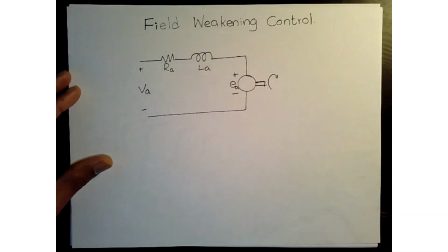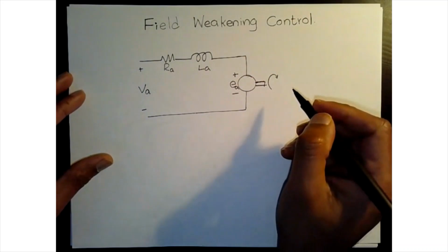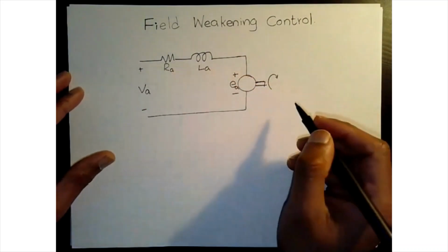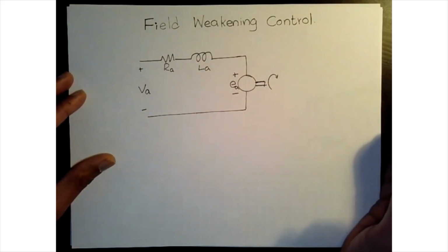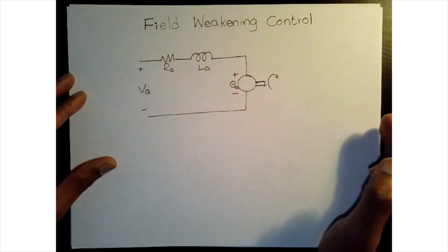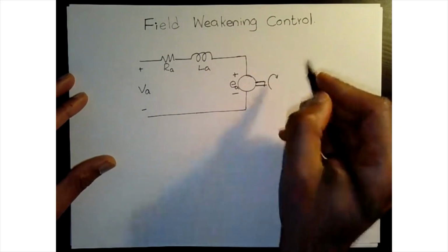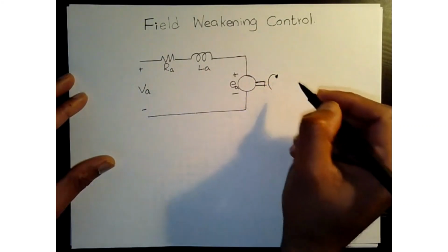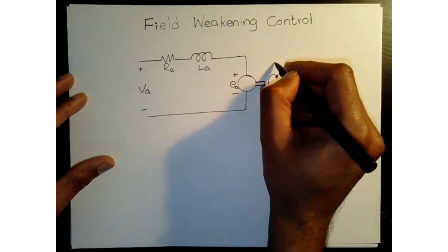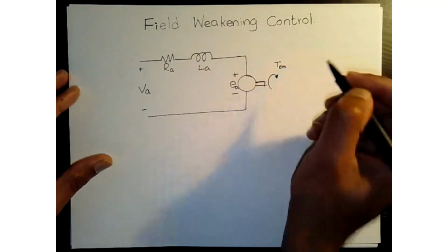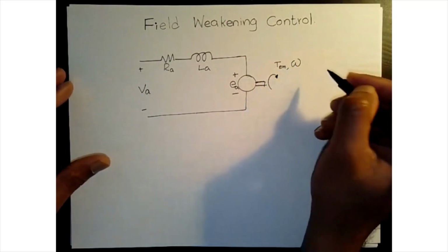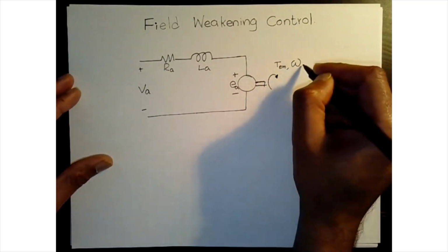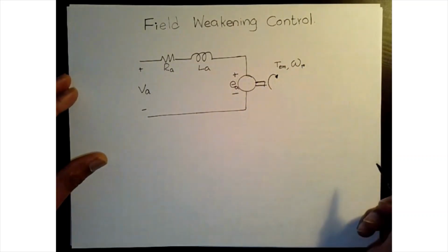Okay, yeah, so the torque constant, of course, right? Torque constant, which in terms of value is the same as KE, the back EMF constant, right? We know that under SI units, KE and KT are the same, or almost close. Not exactly the same, they are very close, right? So by measuring the back EMF constant, we know our